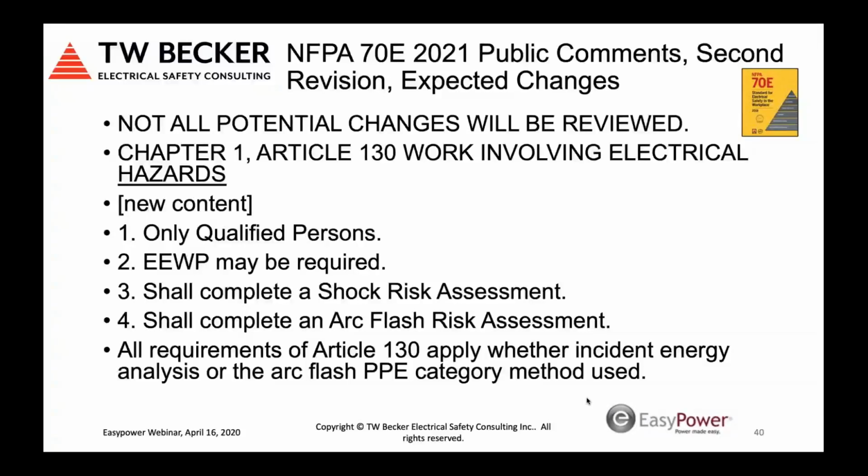The last bullet again, to clarify this whole issue about incident energy analysis versus the arc flash PPE category table method, all of Article 130 or all of Clause 4.3 in Z462 applies whether you're using one of these two methods to determine additional protective measures for a work task arc flash risk assessment. That is all that we're doing with the incident energy analysis, is we're providing electrical hazard data, the incident energy and the arc flash boundary, that's then applied by the qualified person when they complete their arc flash risk assessment.